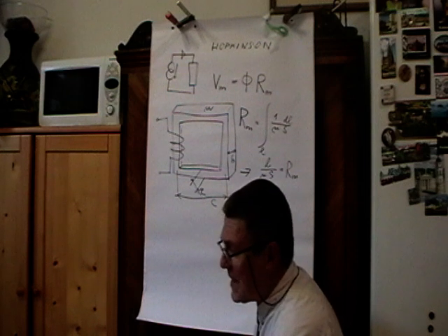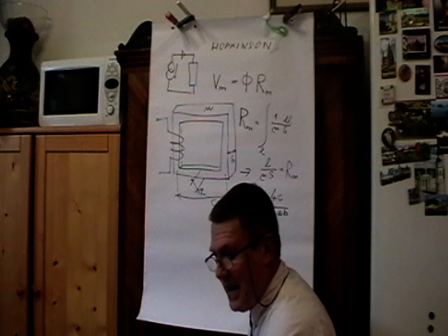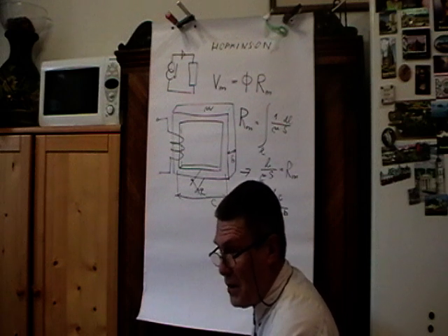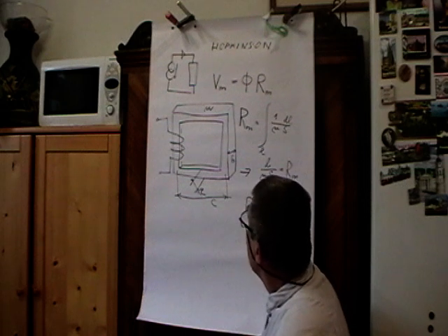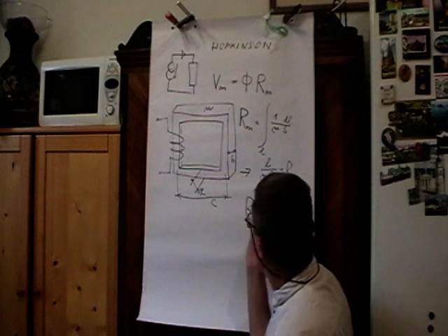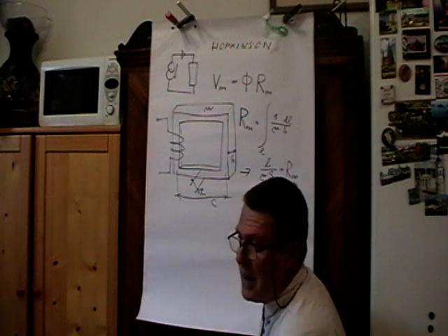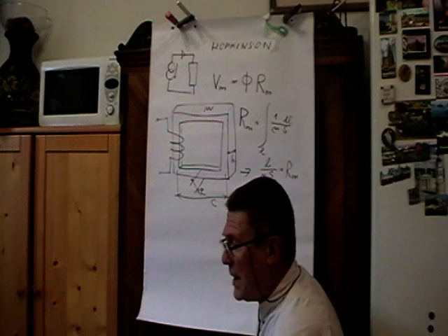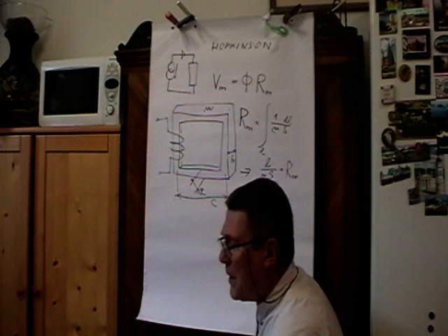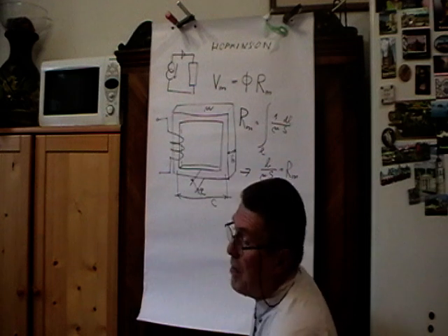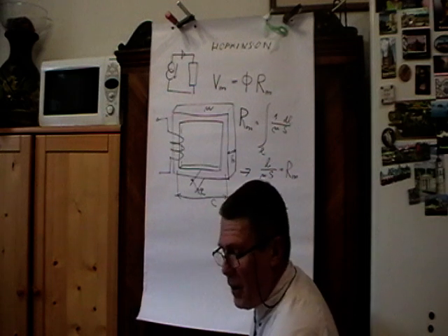But classically we use steel, special steel compounds, to do a good job for magnetic circuits, and 1000 times higher permeability than the air gets us to the assumption that there will be a significant part of the magnetic field conducted through the core. But yes, there is some leakage always.